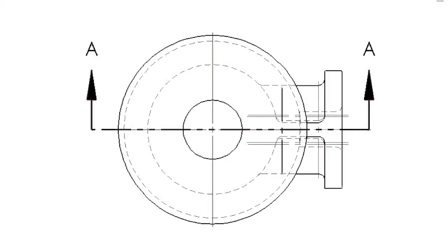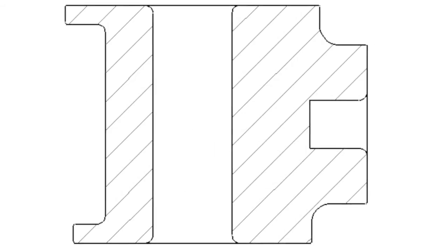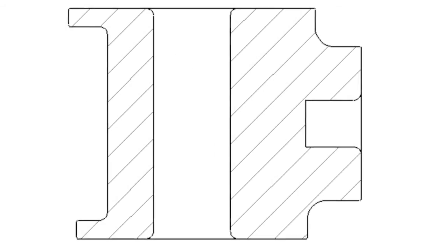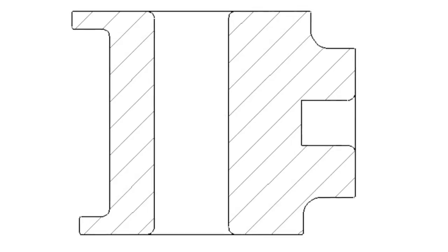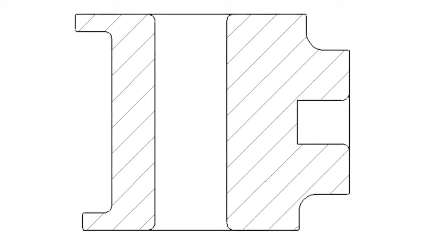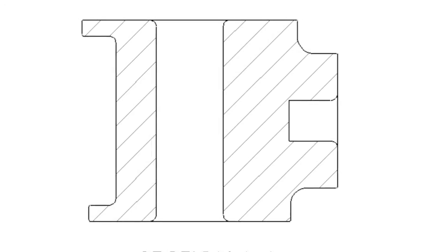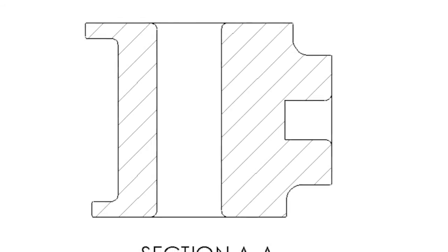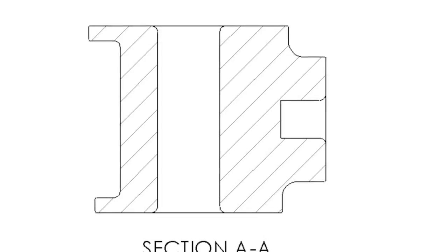A section view is a cut-away view that shows the details of a normally hidden feature. In a section, the feature can be displayed with object lines and properly dimensioned. Section views will be covered in more depth later on in the course.